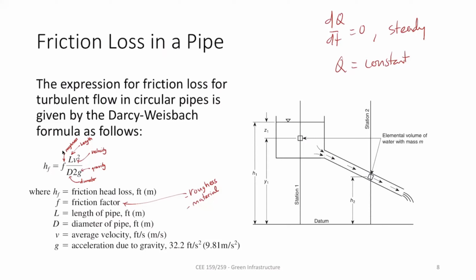Whereas turbulent or laminar flow has nothing to do with steady or unsteady. It's about whether it's moving at slow speed or high speed. So basically they're just separate classifications. They don't really affect each other. Like a laminar flow in the pipe could be steady or unsteady depending on the situation. Yes. So basically, whether the velocity or the flow rate at one location is constant or not, that's the steady flow.